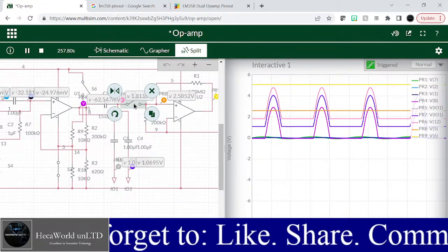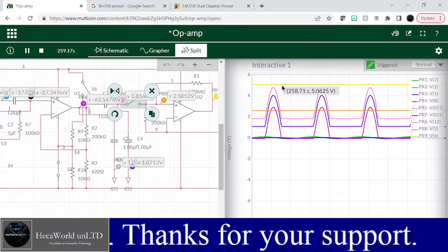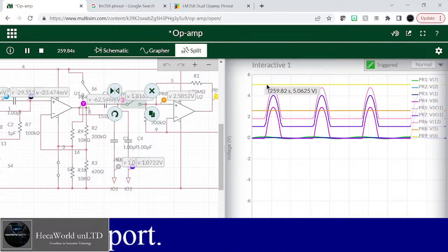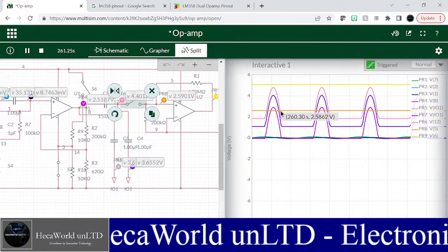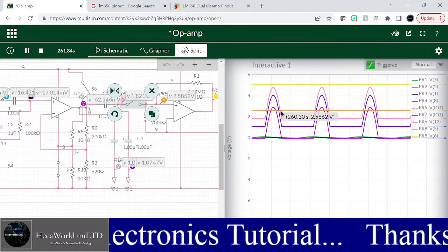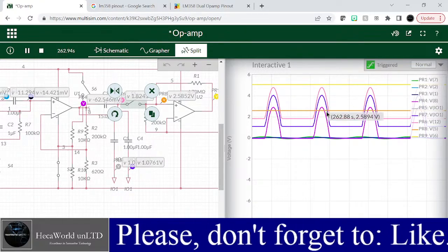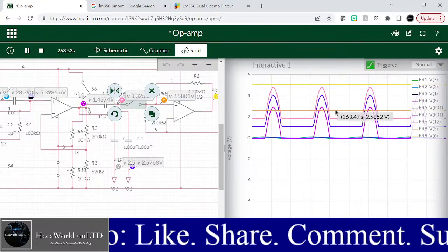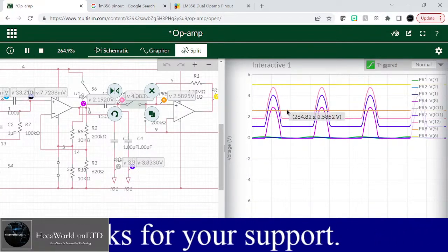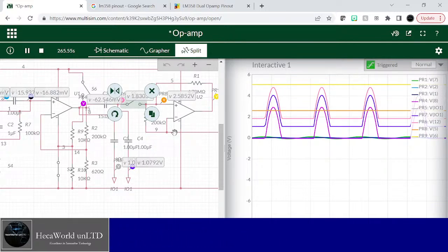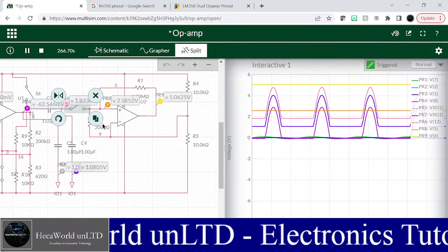The moment I turn that off, the Schmitt trigger, of course, there's no more signal coming there, so it just returns a high, a steady 5 volts. And then this one here, of course, this is 8. So 8 and 9 are just steady signals. 8 is giving me 2.5 volts, which is really, why does it give me 2.5? Why does 8 give me 2.5 volts?